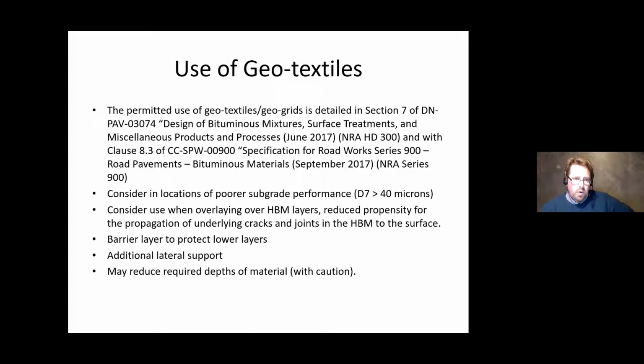In terms of lower layers, they're great barrier protectors to stop the ingress of water. They effectively create a raft that you can carry out your sub-base construction on. If you don't have adequate verges, if you're along an embankment and you're running out of adequate verges that can provide lateral support, it's not ideal. It can be done though. It'll take a bit of negotiation with the TII, but it can be done. It's a bit of a help where you've nothing else. Short of creating a massive embankment or retaining structures, they can hold it together from within.